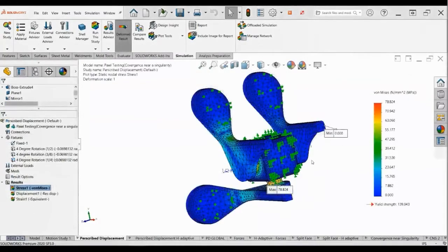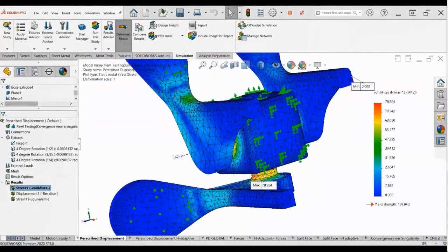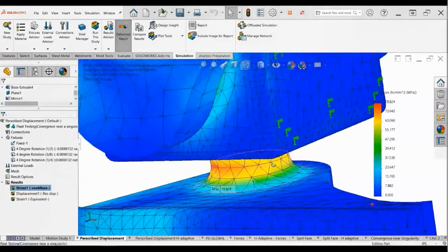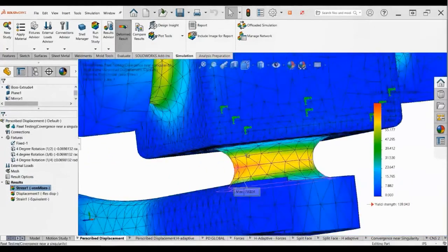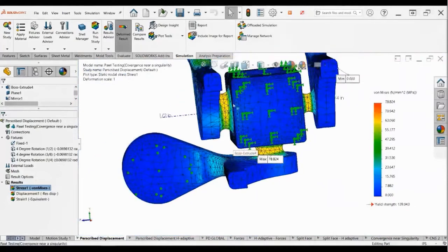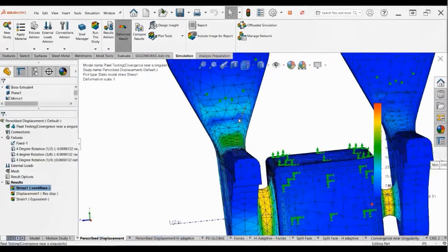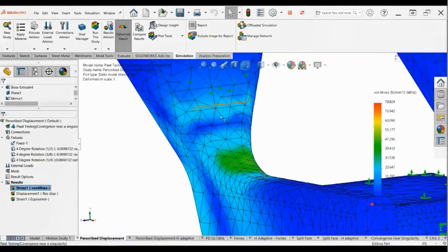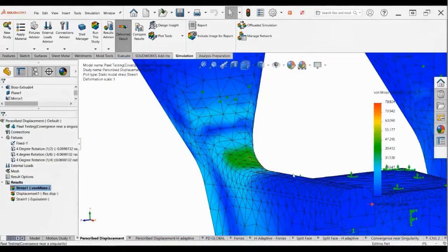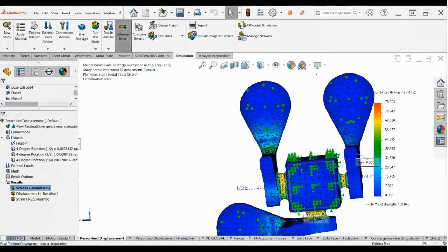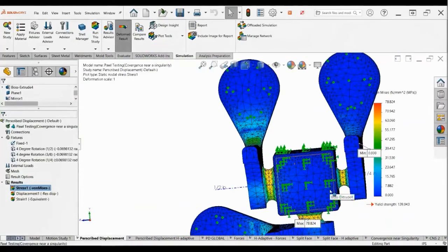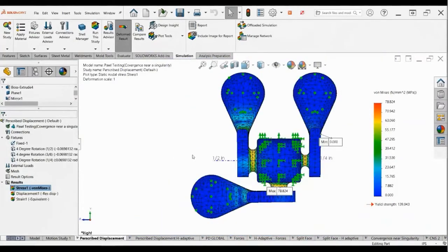Looking at the results, I can see the stress is the highest at the connection points, and that's kind of what I was expecting. Doing a visual inspection of the mesh, we can see a weird stress transition at the end of the thumb piece, which is a cause for concern for the mesh quality. The cylindrical portions do have a smooth color gradient, but that could definitely be improved with some refinement.